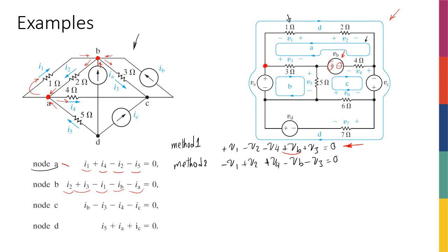So I could have written path E here as well, by the way. Or I could have had a path F starting from this point, going around here, and then coming back, right? So basically ignoring the 3 ohm, the 4 ohm, and the 5 ohm resistors in the middle, just starting from here. Maybe it's better to do it that way. Going this way and coming this way, back to the initial point. So that's path F. And you can define so many other paths. The important thing is that it has to be a closed path.